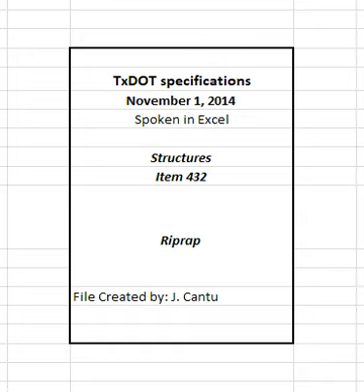Obtain the desired distribution of the various sizes of stones throughout the mass by selective loading of material at the quarry or other source or by other methods of placement that will produce the specified results. Rearrange individual stones by mechanical equipment or by hand if necessary to obtain a reasonably well-graded distribution of stone sizes. Use the bedding thickness shown and place stone for riprap on the bedding material to produce a reasonably well-graded mass of riprap with the minimum practicable percentage of voids if required on the plans.